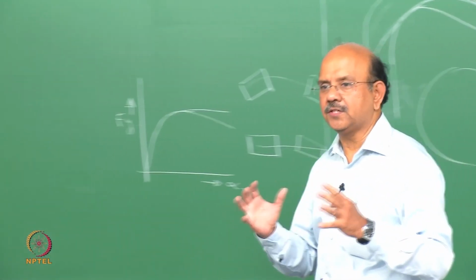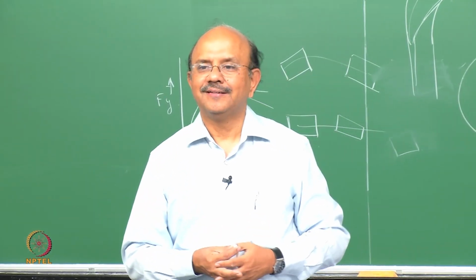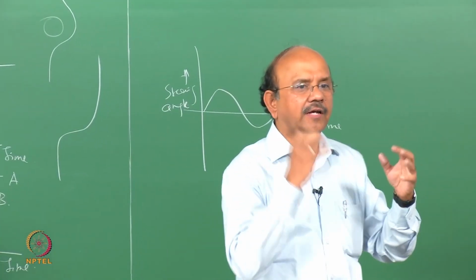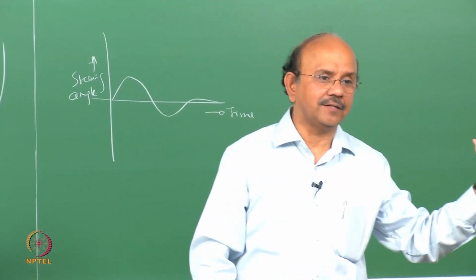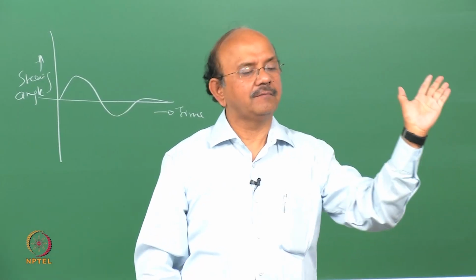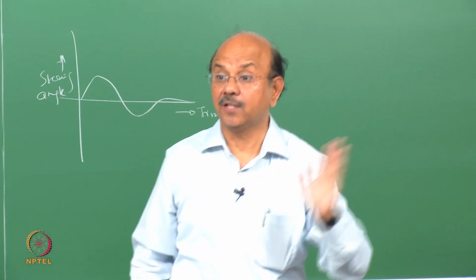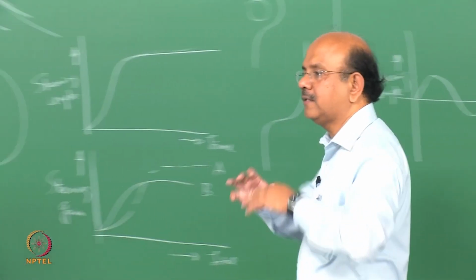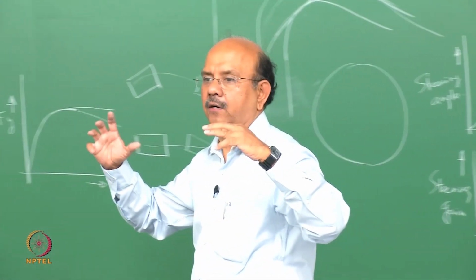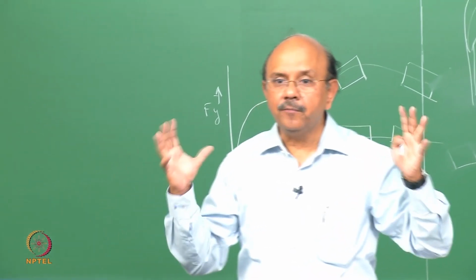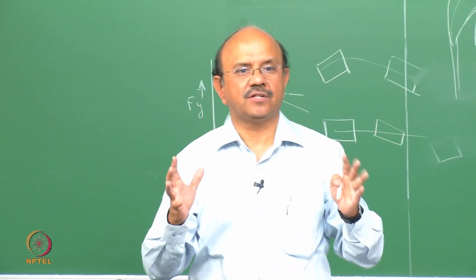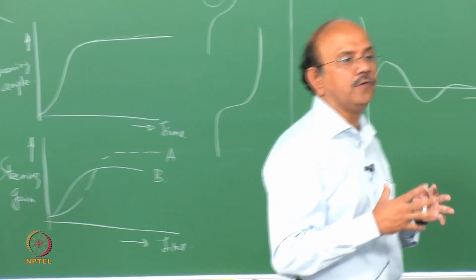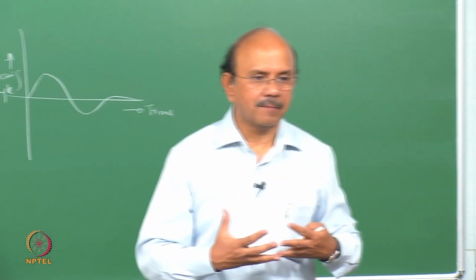No. The most interesting fact that comes out is what I had presented some time back. The type of characteristics of the car tested by this group is more oversteer, but the cars tested by the Japanese, I repeatedly said, are understeer. In other words, it is not that there is a monotonic increase of these parameters. It simply means that there is an optimum range which would give you the best performance.